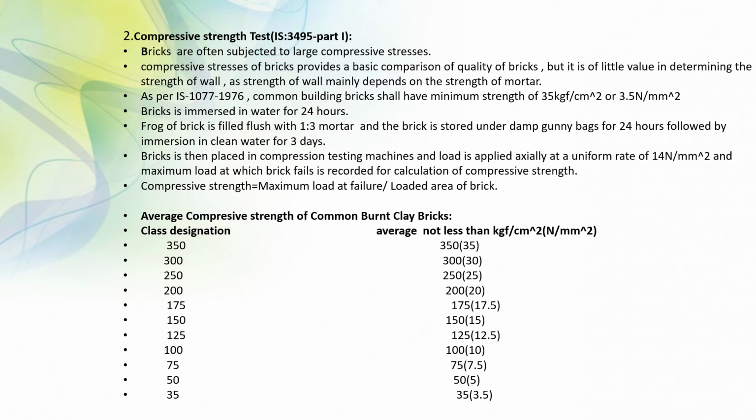Next, I will discuss the compressive strength test, IS 3495 Part 1. Bricks are often subject to large compressive stress. The compressive strength of brick provides a basic comparison of the quality of bricks, but it is of little value in determining the strength of a wall.